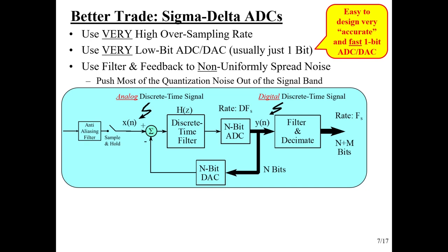This is modeled after a figure in that diagram, or in that paper. So we've got our anti-aliasing filter out front. Now I should say that that should filter still just to the frequency band of the signal, because we don't want any extra stuff of the signal coming in, although we can tidy it up over here as well.